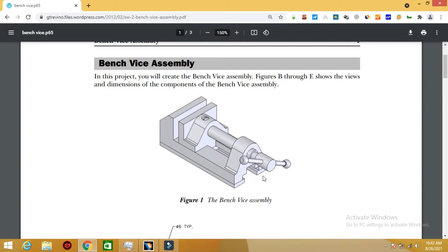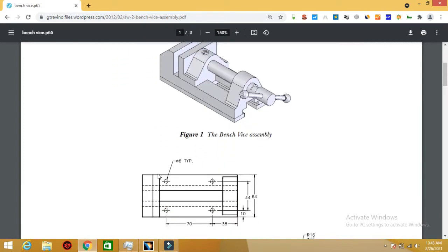Similarly, if you look from the right, you will see this face, a little bit of this face in your view. Like this is your top view, you can see this face which is here, this slant surface, this horizontal flat surface, and this curved surface. Because you are looking from the top, the curved surface will look like a rectangular shape.